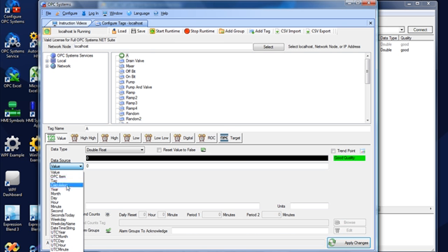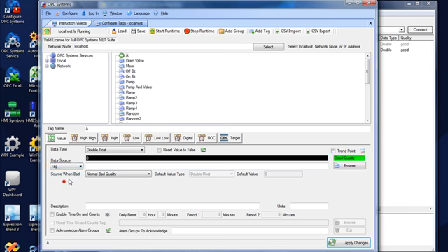You could also use the data source of calculation or the data source of OPC item if you also wanted to use the product feature OPC client.net. This would have the benefit of being able to write back to the remote service if you were going to use the data source of OPC item. With the tag data source of tag or calculation, it becomes a read-only tag.